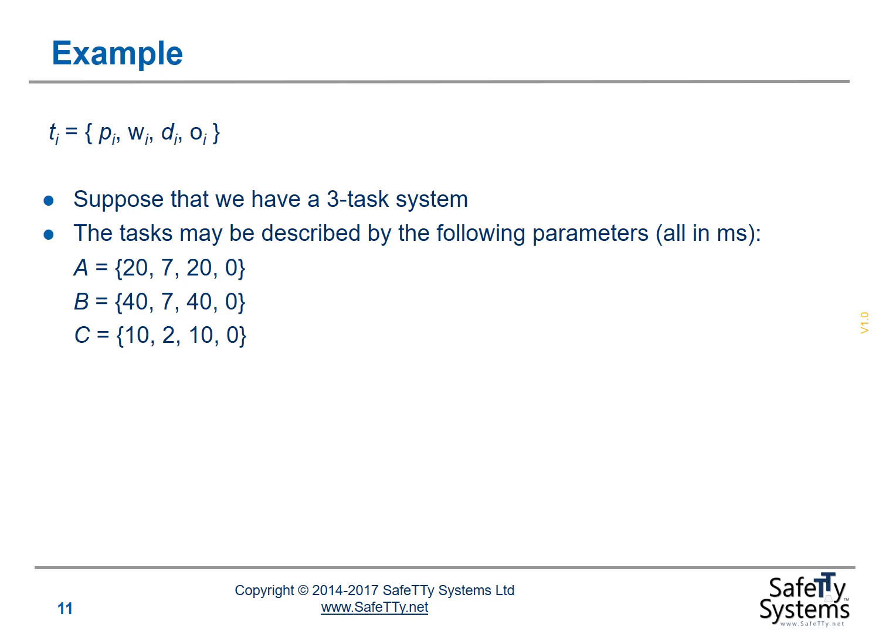So what we're saying here is that the deadline is equal to the period. We're not saying these tasks have any significant jitter requirements. We're just saying that each task must complete before it's scheduled to run again. We're giving each task an offset of 0, and we've got a worst case execution time that's significantly less than the period.